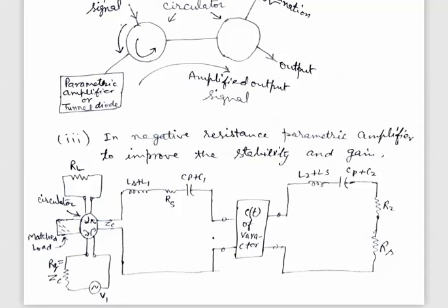circulator. If a circulator is not used, then multiple reflections within the guide will take place that will cause instability of the system, and we could not take gain at the same frequency as the input frequency omega s.